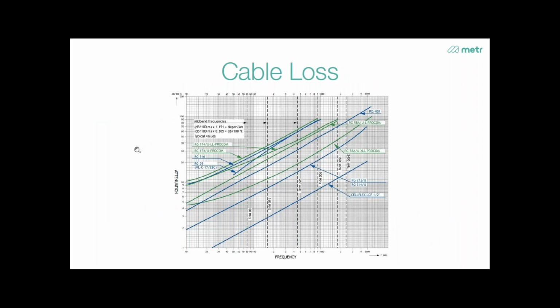And for the cables, here you see a chart on how to select a good cable, for example. You have to be aware of which frequency you're using. In our case, you can see the line in the middle roughly where we have 900 megahertz-ish. What you can see here are different cables and how they behave, what their loss is in decibels per 100 meters. That's the scale on the left-hand side. And you can see all those curves of those cables that you can usually find in shops, right? RG58 and stuff like that.